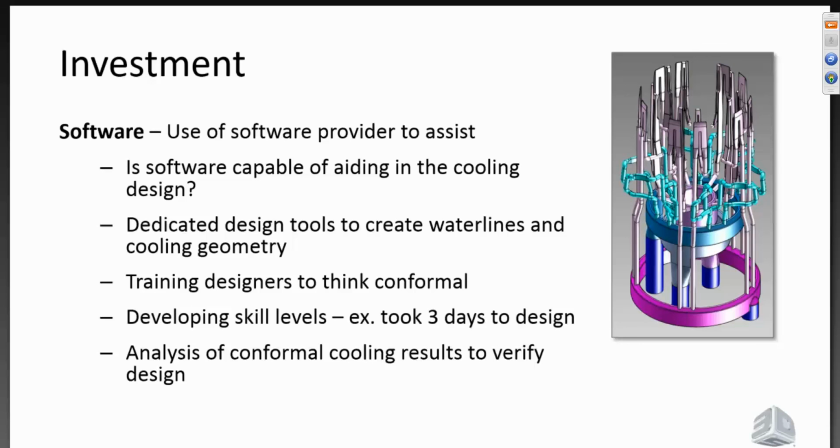That example, again, just to fully disclose to you, the designer who worked on that, he's an engineer that we work with here. He says it took 3 days to design that water line that you see on the screen there. Bear in mind, that's more than just offsetting faces and doing all the CAD work. That's taking the water line, taking it through analysis software like Moldex, checking to make sure that the water line is going to take the heat out, there are no hot spots. If there's something that doesn't look right, it's going back, tweaking it, adjusting it, going back through the analysis again. So it's more of a process of 3 days rather than just sitting there actually building geometry for 3 days.